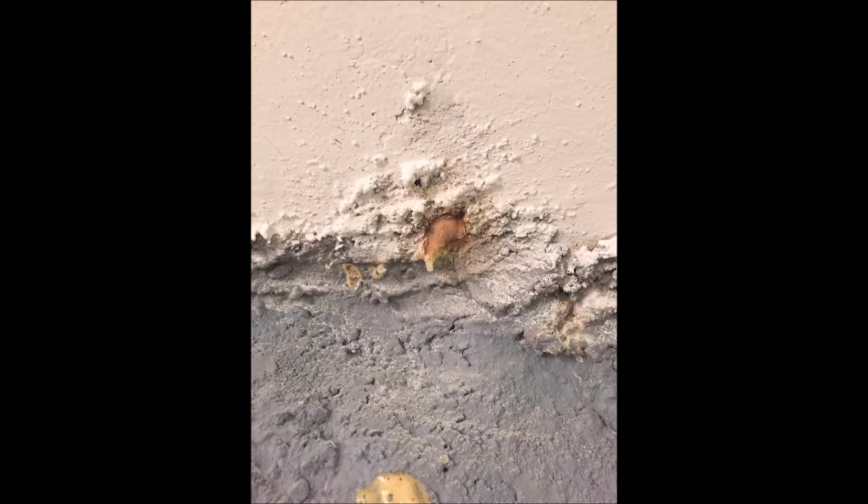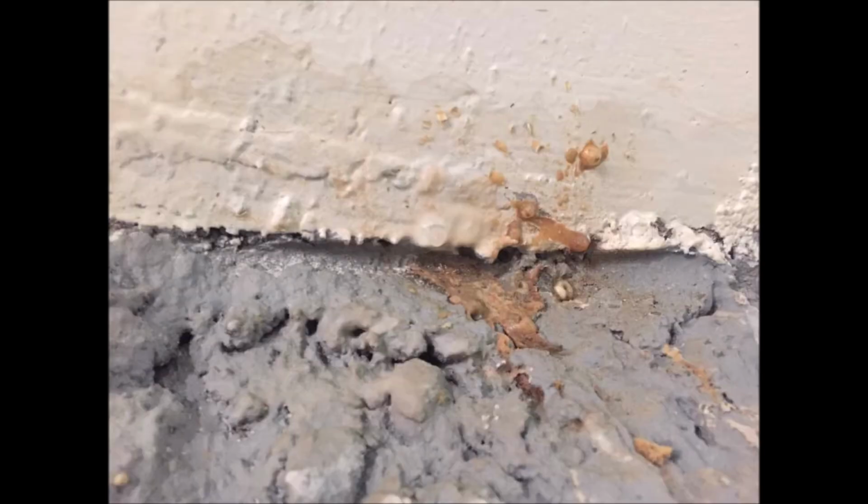When efflorescence is due to the rising of salt solution through capillary action from the subsoil, the only remedy is to provide bitumen or metallic seals in the wall above the ground level so that an effective barrier to the capillary action is created. In this case, we are going to use all these 3 remedies.